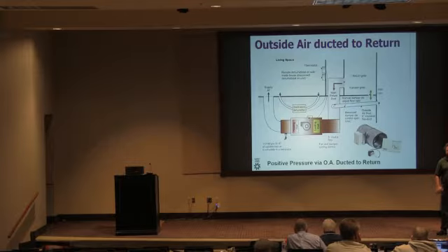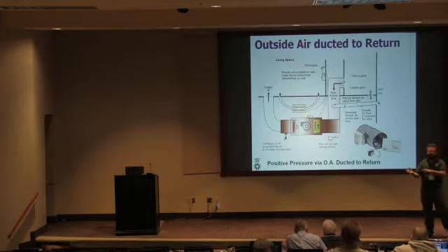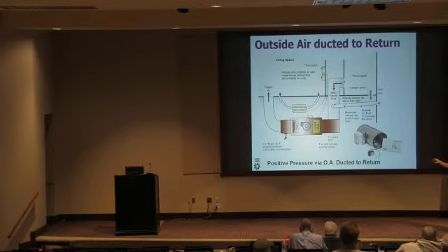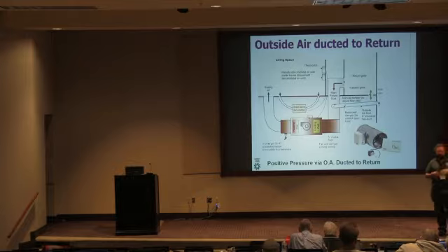But the question I have is, is there an average time that it should run? Because I'm hearing from people it's running 35 to 40 minutes on an hour. Again, you can do ventilation continuously or intermittently. If you do it continuously, then you take the ASHRAE 62 calculation, you look at the capacity of whatever your outside air system is, which for a system like this is basically determined by the size of this duct and how long the damper is open, and you match the CFM, cubic feet per minute, from ASHRAE.